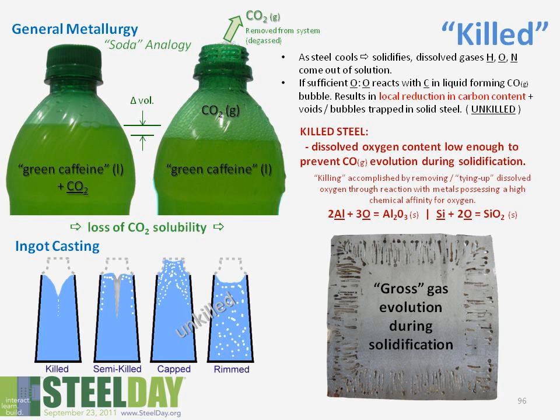The question often comes up, what is a killed steel? What do we really mean by that? Well, let's look at the soda analogy. If we take my favorite green caffeine soda, as delivered by the manufacturer, it has carbon dioxide dissolved in the liquid. It's not really apparent. You get a few bubbles every now and then. But if I was to shake this up and release the top, this dissolved carbon dioxide comes out of solution as gas bubbles. It escapes, and I have a volume reduction. That volume reduction is due to the loss of that carbon dioxide in solution.